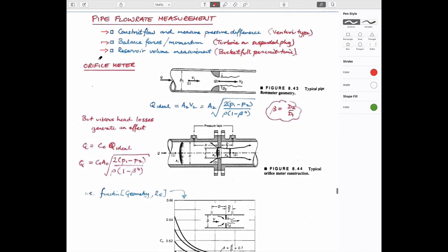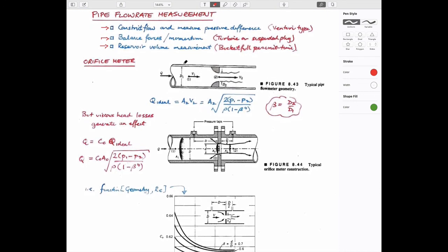I suppose if you talk about constricting flow and measuring pressures between upstream and downstream, then the issue is that you'd like to have a constriction in here that gives you a predictable flow at all flow rates, all Reynolds numbers. And I suppose you don't want such a huge constriction that you spend all of your energy pushing the flow through there because of the big head loss as you get across here. So you'd like it to be a low head loss, which means that you probably don't want much of a constriction. But of course, if you have a really low head loss, then your resolution of being able to measure the pressure differential is going to be tough. And so there's a balance between each of those.